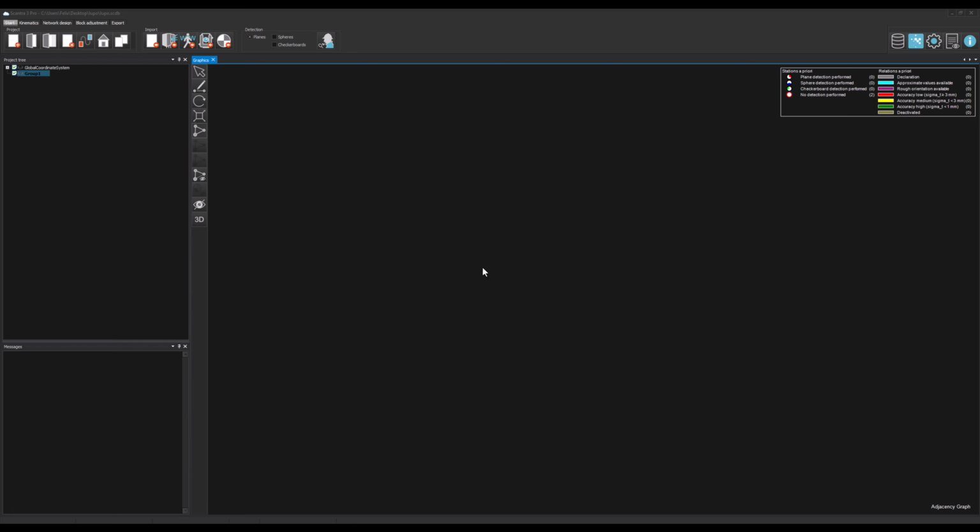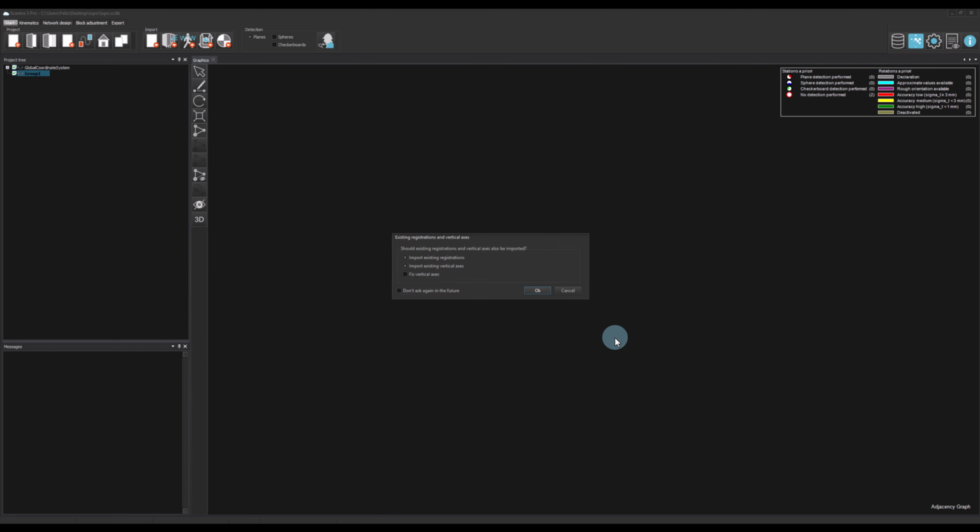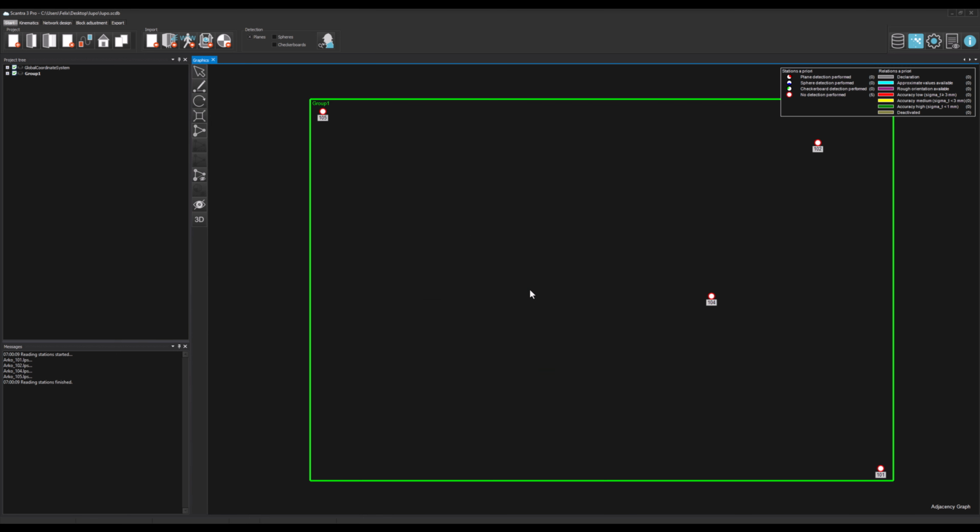LupoScan's file structure does not use an explicit project file. Instead, information about group associations and digitized points are provided by additional files that refer to individual scans. LupoScan point clouds of static scans have an LPS suffix and need to be imported first under Import Static Scans in the Import Group box. Points can be imported under Import Points from LupoScan.